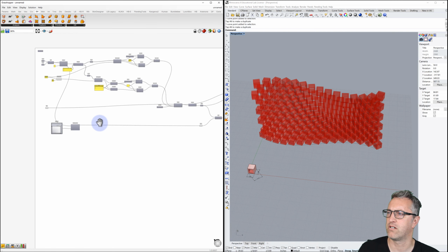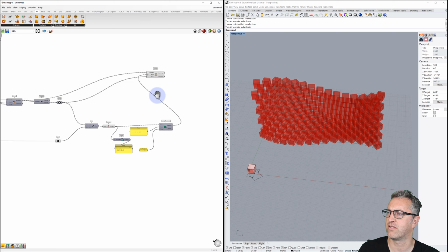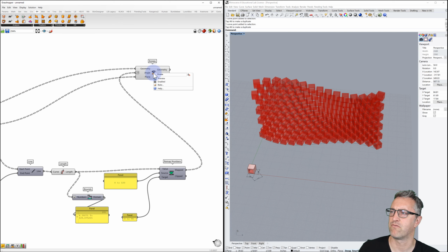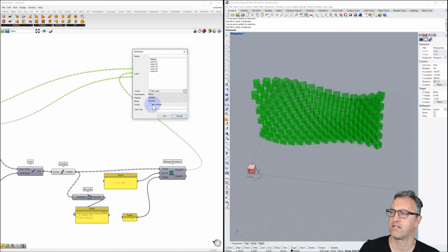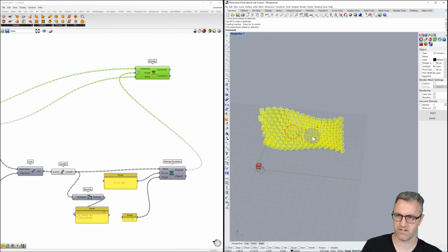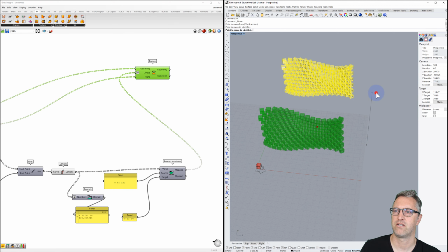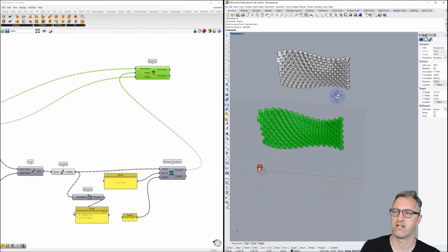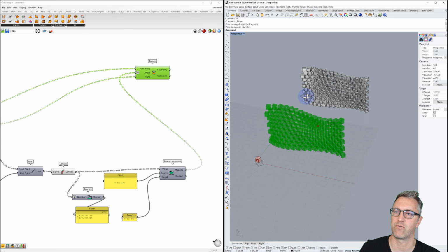So one nice thing now that as you work on this, if you right click the rotate, we can bake this and group these together, and then it's easy enough to move these out of the way. You can change your wall, you can change the way that your elements are mapped, and then you could export another one.